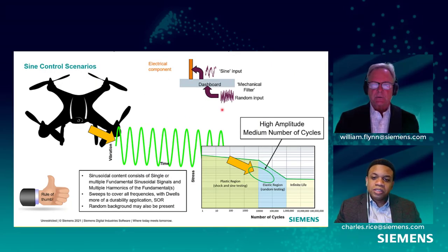Another application here, but I had a quick question, Charles? Yeah, just about the dwells for durability. Would they normally dwell at the natural frequencies of the structure, or maybe at a frequency related to an operating speed? Well, it's typically at an operating speed. Helicopters are a really good application, and they try to characterize the rotational frequencies and identify those ahead of time.